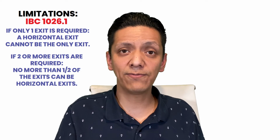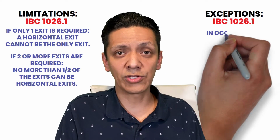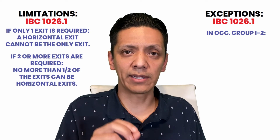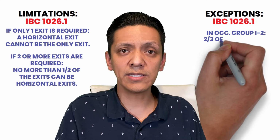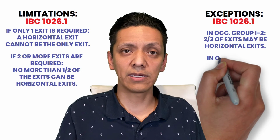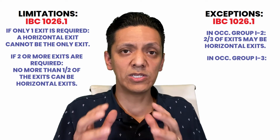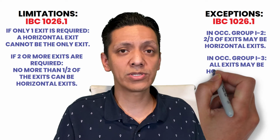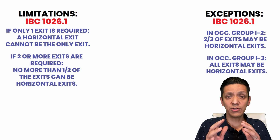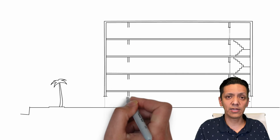We've already mentioned it before, but there are 2 exceptions. Do you remember? One is if you have an I2 occupancy group, in which case you can bump that up slightly so that if you need multiple exits, 2/3 of your exits can be horizontal exits. And there's the exception for an I3 occupancy group. Do you remember what that is? Well, in this specific scenario, 100%, or in other words, all of your exits can be horizontal exits. And those are your limitations as to when you can use and how many exit doors you can use.